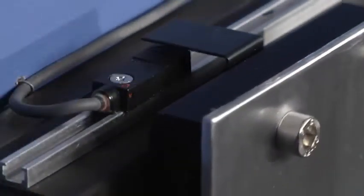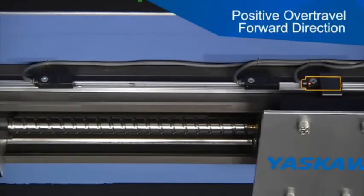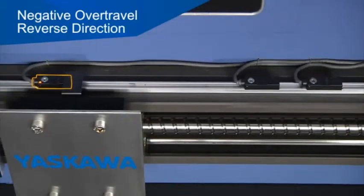Overtravel inputs can prevent costly damage. Without it, moving parts of the machine could be allowed to crash into one another. Now, the positive overtravel sensor is connected to the amplifier input that stops motion in only the forward direction. The negative overtravel sensor is connected to the amplifier input that stops motion in only the reverse direction. So you can see that if these sensors get switched around, or if the direction of the servo doesn't match the direction of the machine, the motor might not stop at the overtravel sensor. Damage or even injury might result.